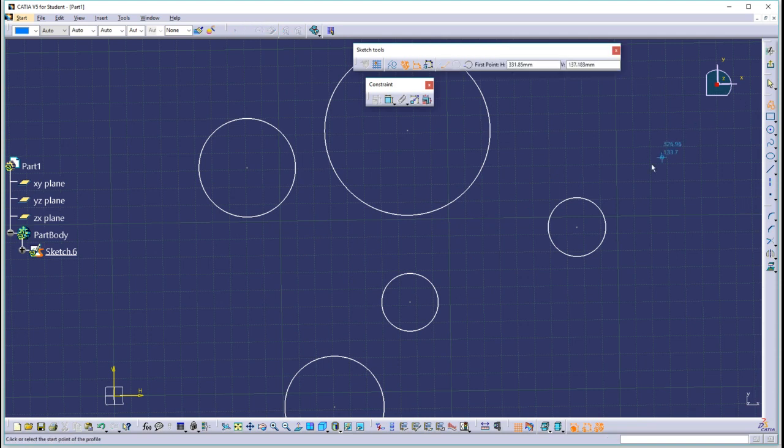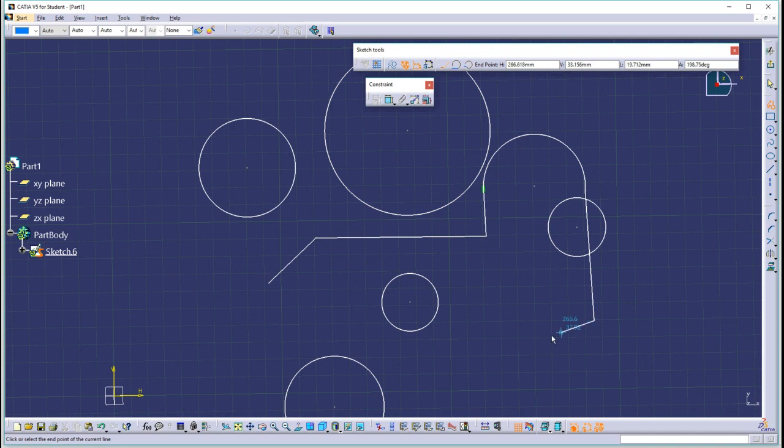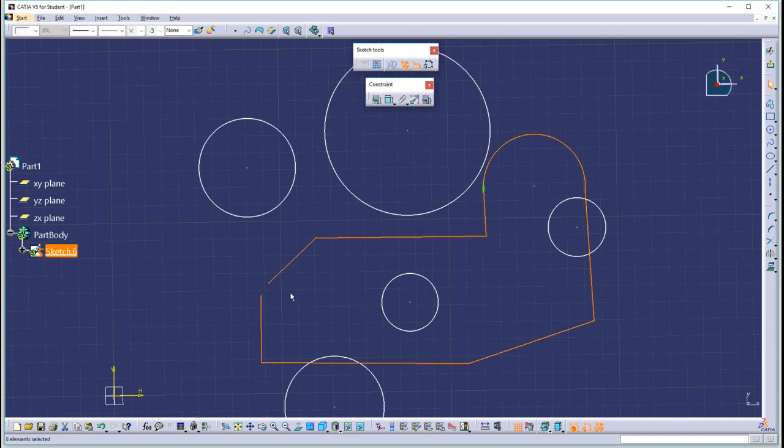Now when I select my profiler, I'm going to hold the Shift key down. And now when you hold the Shift key down, you're able to draw without picking up any of those constraints. However, notice that you are not picking up the horizontal and verticals either. So you lose some and you gain some. I'm not a big fan of the Shift key, but here's where I am a big fan: occasionally when I'm drawing, I'll Control Z back out of this. You can use it at will.